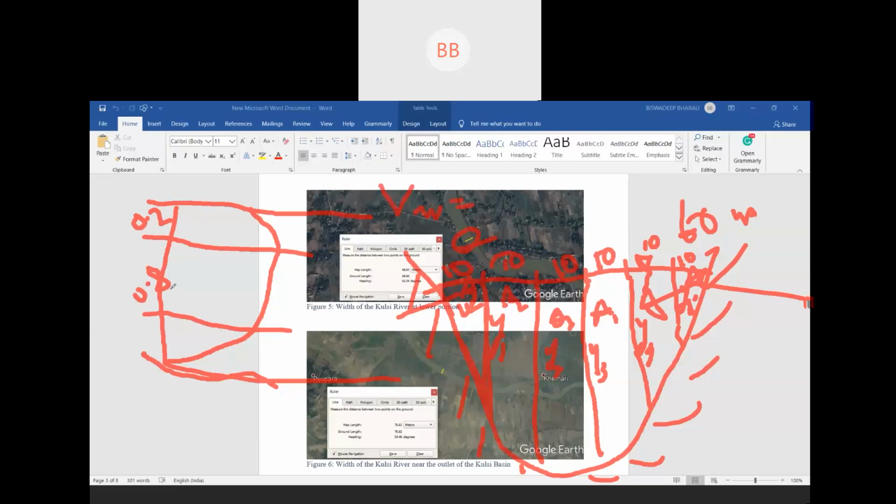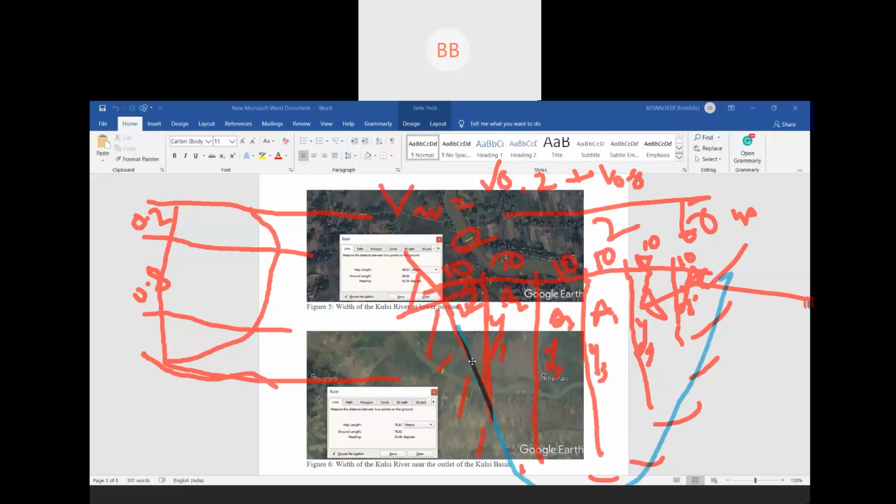So they are saying that to find the average velocity, you have to find the velocity at two sections, that is 0.2 and 0.8, and you take the average of both. Then you will get the average velocity for a particular section. So you have to use this equation for each area. For this particular area, you have to find the average velocity using this concept.